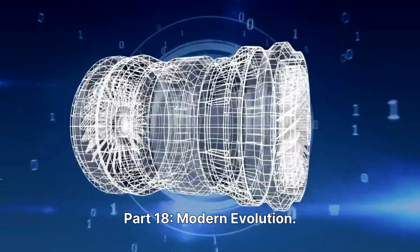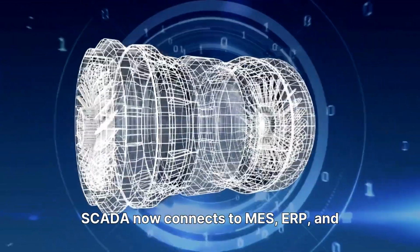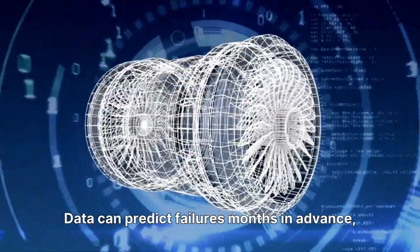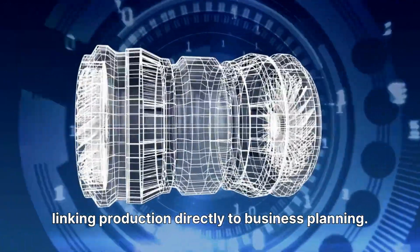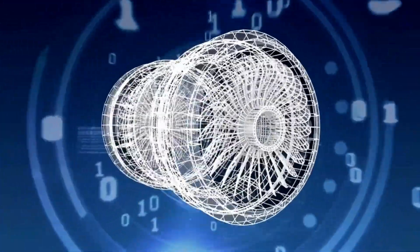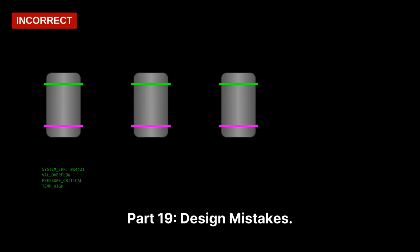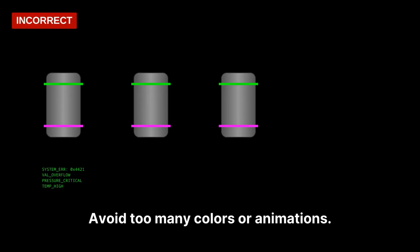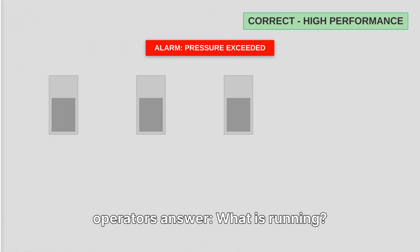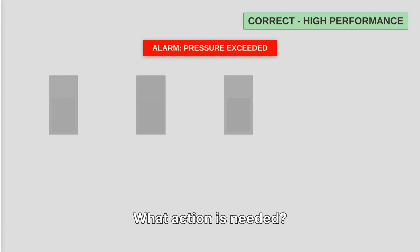Part 18. Modern evolution. SCADA now connects to MES, ERP, and AI models. Data can predict failures months in advance, linking production directly to business planning. Part 19. Design. Design mistakes. Avoid too many colors or animations. Good design is simple and clear, helping operators answer, what is running, what is abnormal, what action is needed.